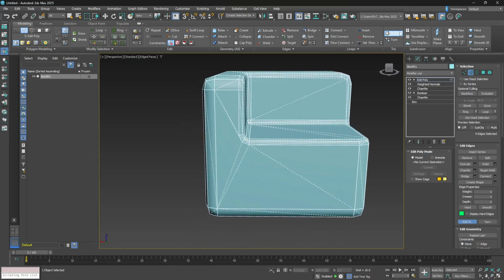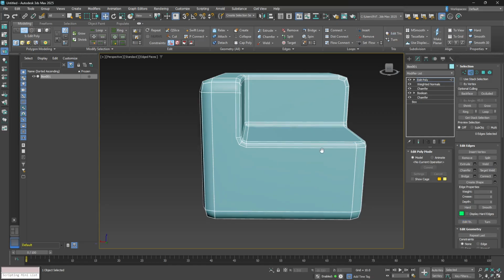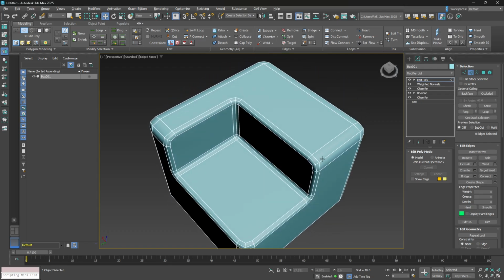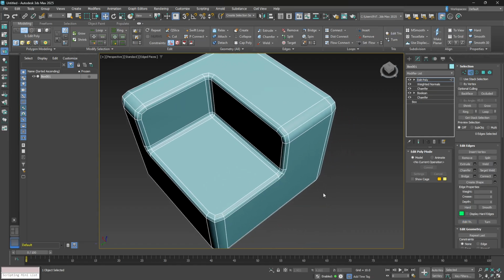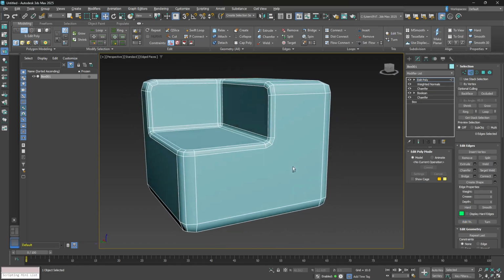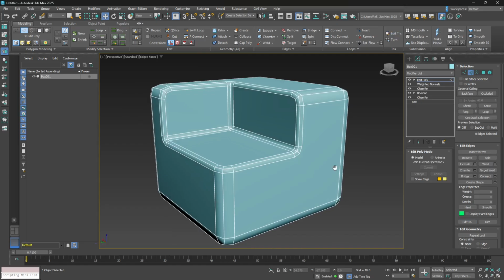But what edit triangulation allows you to do is you click on a corner, a vertex, and you can click on another corner and you can reroute all the triangulation. So you can do this on Ngons. You can't do this inside of Blender unless you actually triangulate your mesh with a modifier and apply it. So it's one of those weird things that doesn't seem like a big deal until you're dealing with really low poly game models and trying to optimize them. It's something that you'll end up wanting to utilize more than likely.